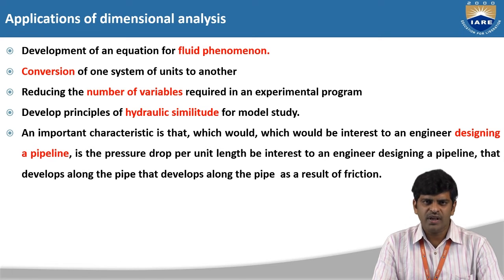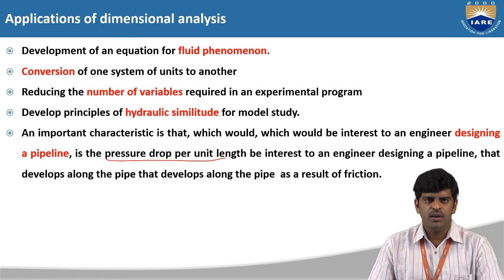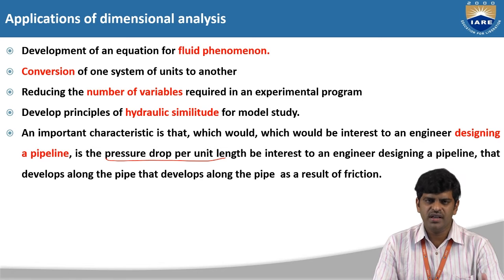Next, the important characteristic is that when we are going to design a pipeline, like pressure drop per unit length, as we have discussed, in the case of the water distribution system, the pressure is an important parameter to be considered. When we are going to fix the quantity of the pressure, similitude is very much essential, and therefore the concept of dimensional analysis finds its applications in the similitude process.